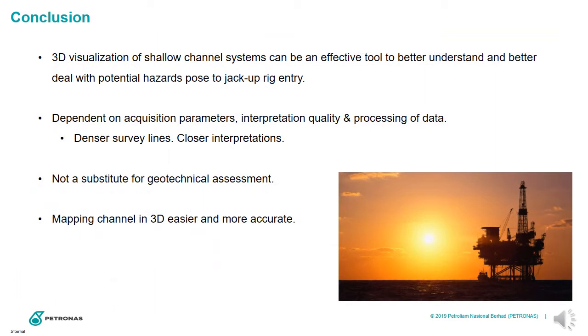In conclusion, 3D visualization of shallow channel systems can be an effective tool to better understand and deal with potential hazards posed to jackup re-entry. However, there have to be considerations on acquisition parameters, interpretation quality, and the processing steps involved. Denser survey lines and closer interpretations are required to get a more accurate picture of the subsurface channels being mapped.